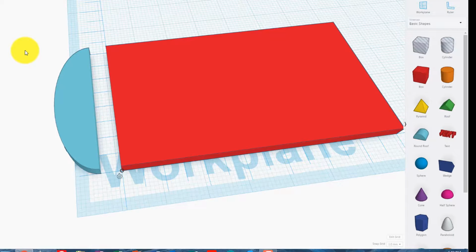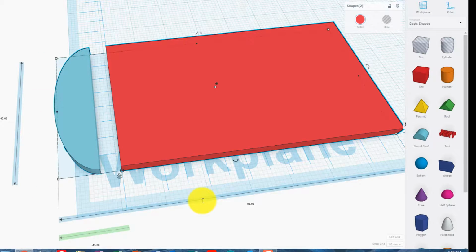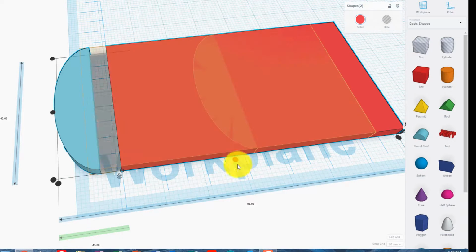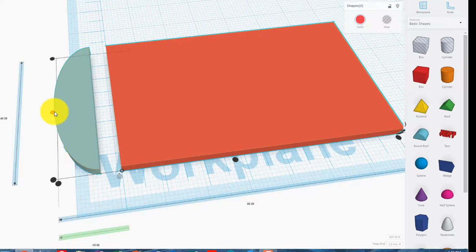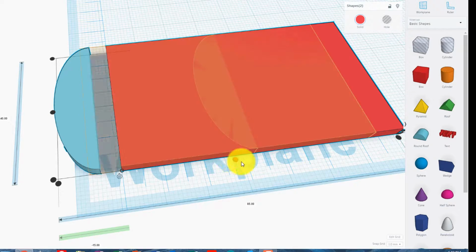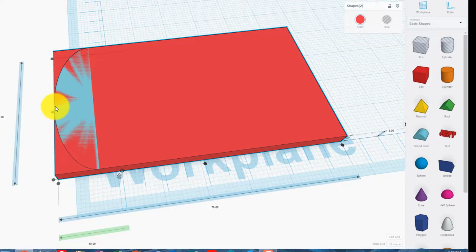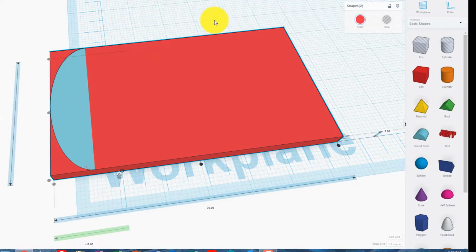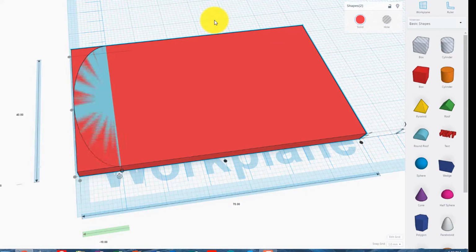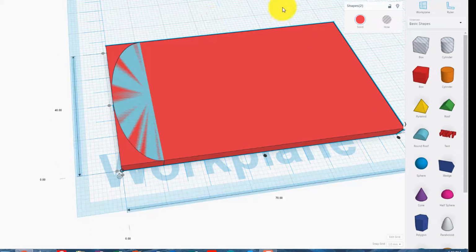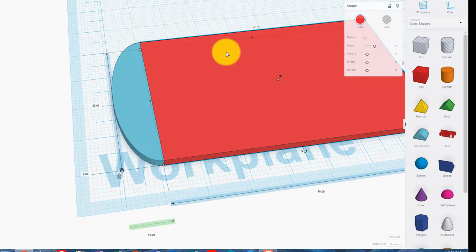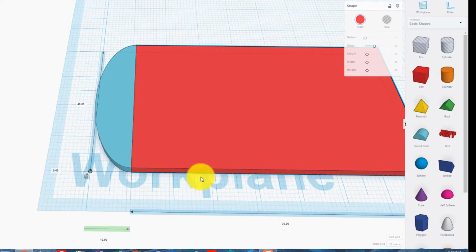The easiest way to do that is to grab both of those. Just select them, and we're going to go up and use the align tool. I click the align tool and I have all of my align buttons here. This is the Y plane, and that's all I want to do at the moment. I could put them there like that, but see, that would align both those edges. You could do that if you wish, and then what I can do is move them across, and I'm going to have to click on one of them and move it away. That's it, like that. Good, excellent.